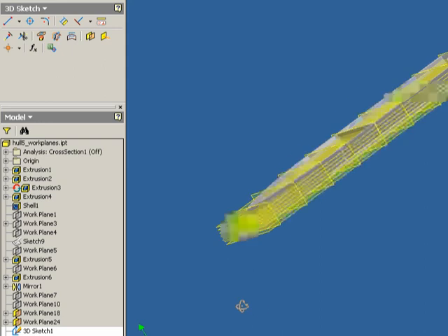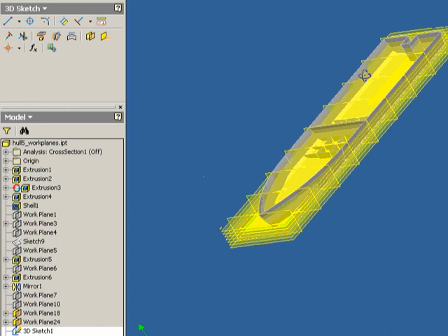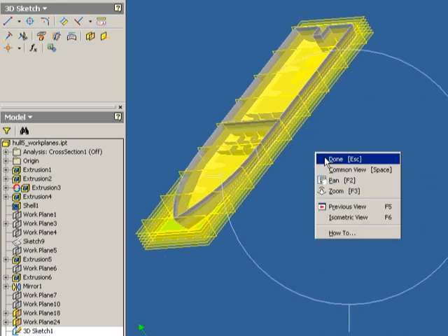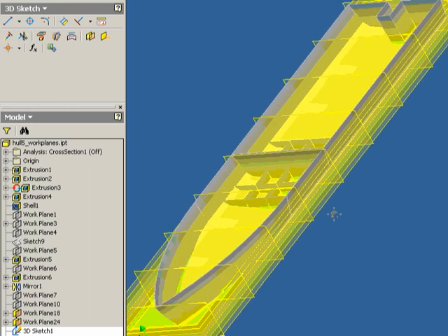I'm going to maneuver my boat around so I can calculate the port values. The reason I'm going to calculate my port values first is because they've got a mirror command in your spreadsheet that the shipyard gave you that will calculate the half-breadth distances for the port side, and the mirror command will simply copy and paste it over to the starboard side for you. However, if you start with the starboard side, it won't mirror it to the port side. So we have to calculate the port side values first.